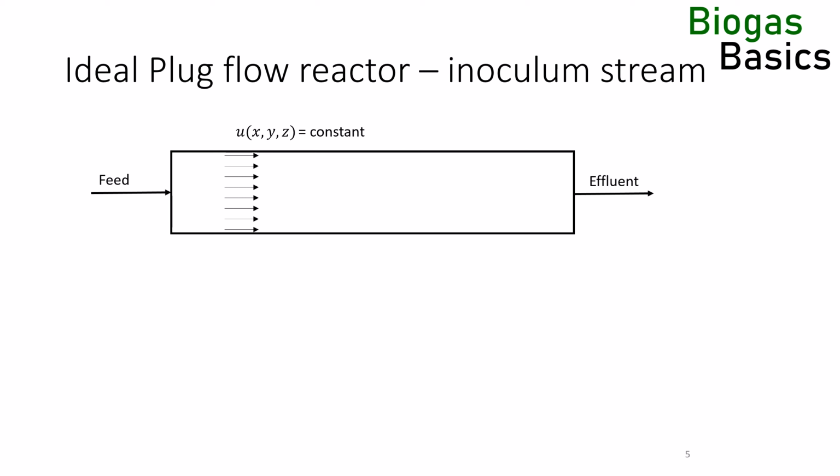Also, fermentative bacteria would outgrow acidogenic and methanogenic microorganisms, and the reactor would acidify. This is what happens when crops are ensiled. The fermentative bacteria outgrow acidogens and methanogens, and the pH quickly drops, so their growth is inhibited. And eventually, even the fermentative bacteria are acid inhibited, and the silo stock is stable and can be stored. A silo is a batch reactor, but we learned already that batch reactors and plug flow reactors have similar properties.